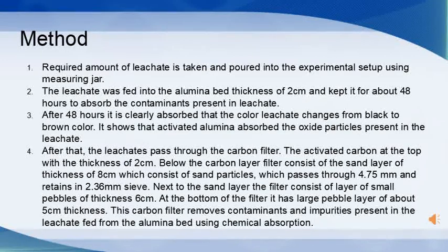Then I would like to talk about method. The required amount of leachate is taken and poured into the experimental setup using a measuring jar. The leachate was fed into the alumina bed of thickness 2 cm and kept for about 48 hours to absorb the contaminants present in the leachate. After 48 hours, it is clearly observed that the leachate color changed from black to brown. It shows that activated alumina absorbed the oxide particles present in the leachate.